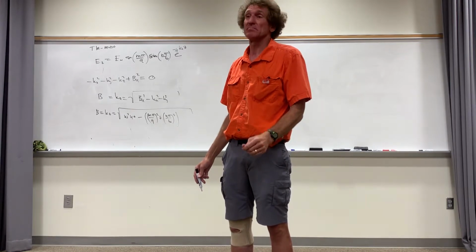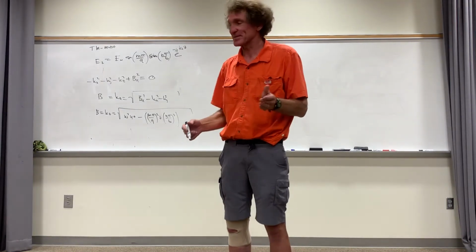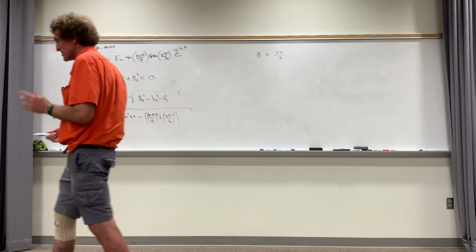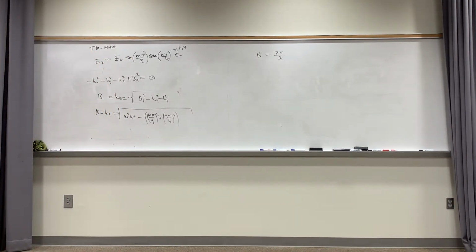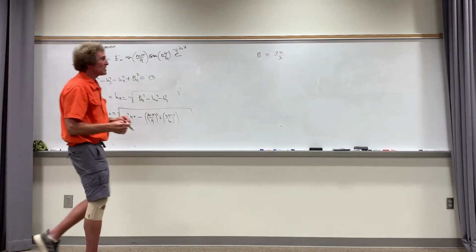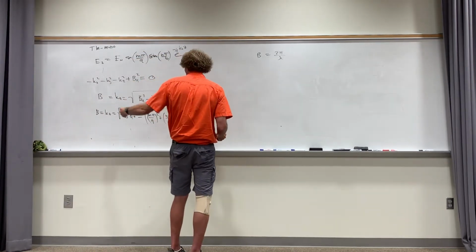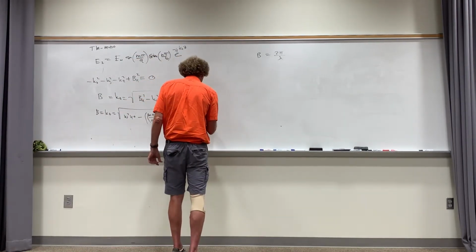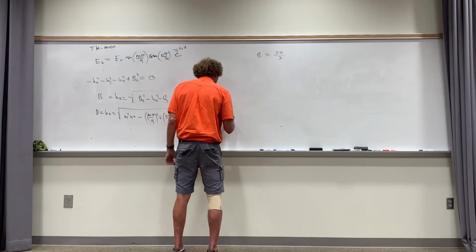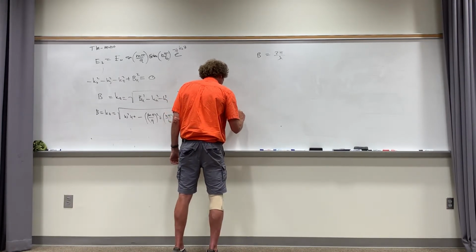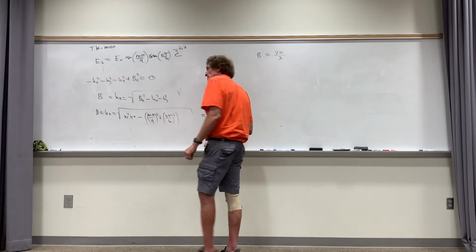Basically, it doesn't fit. And the real truth about this is Dr. Shumpert, a professor years ago, used to say this. He goes, it means the wave is too fat. It is too low of a frequency, or that sinusoidal shape just won't squeeze into the guide, so it'll be shorted out by the guide. That's what it comes down to. And what that really means is this beta goes to 0, and put this down at cutoff. This is the lowest possible frequency that you can go at.